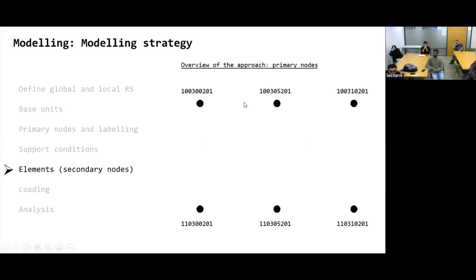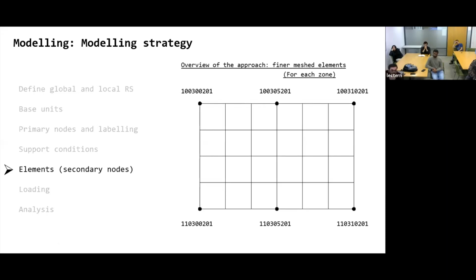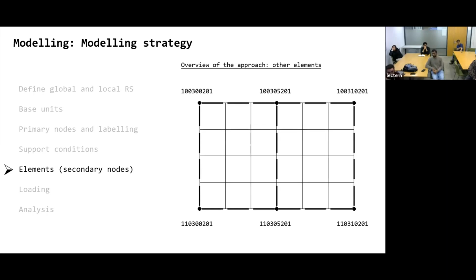So the first thing that I do is create the shell, and it will be a procedure that will generate the shell, and the shell will create the nodes. Then, once I have that, I define the beam column elements, and now the beam column elements are simply defined in between the existing nodes. So I don't have to worry anymore about new nodes unless I have something strange. And we will see a case where I need new nodes after defining the shells. And then I define the beams in the other direction, and then the columns. And then my model is completely defined.